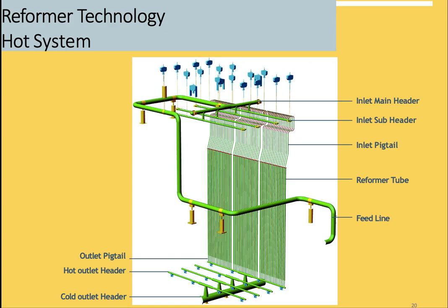Okay, the root cause for this criteria, which is tube rupture or tube leaking, can be long-term overheating, because the heat distribution using this huge number of burners is very critical. It can also be metal creep or carbon attack, or poor metallurgy. Is this a poor metallurgy through this metal tube? It will be very, very critical and can lead to tube rupture. The corrective action is immediate emergency shutdown, nitrogen purge, tube inspection, and review the flux design.